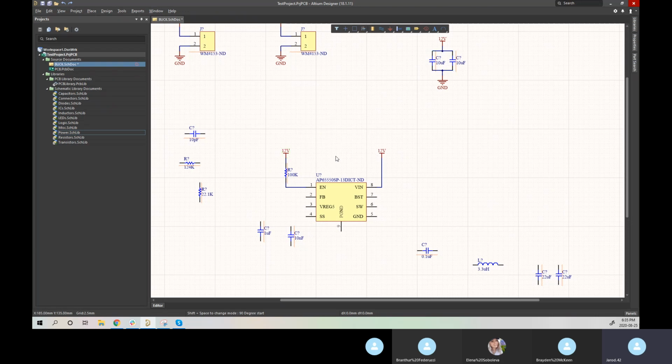This is purely just a matter of how you want to lay out your schematic. I find it cleaner when you break it off, so you have multiple power nets. That way you don't have wires coming across the full thing and potentially overlapping on each other.